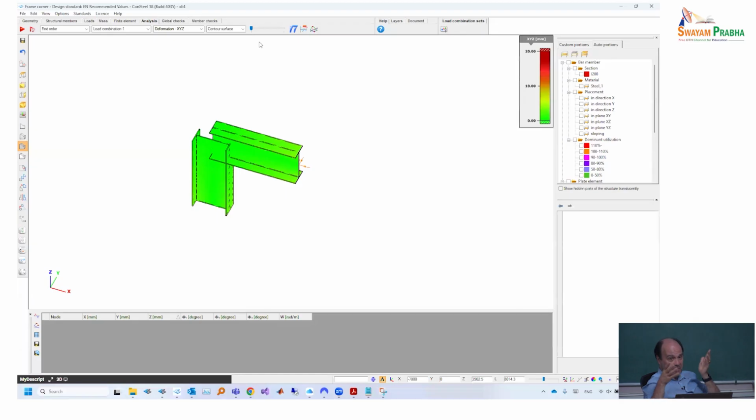So exactly the same way as we transfer a bending moment, we can mathematically do the same also with the warping. It's also very important for the bending moment. Typically, all the finite element calculations assume that this Bernoulli-Navier hypothesis is valid, that the cross sections which are connected are rotating together. But imagine we have a very deep I section and a shallow I section, and you don't put any stiffener into the other element, and you apply a bending moment to this one. What is the chance that they will nicely rotate together?